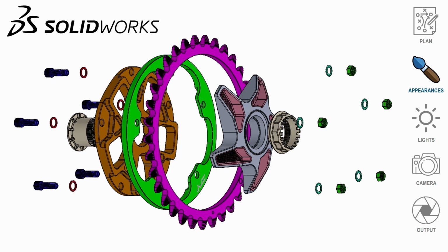Usually what I do in this case is, in SolidWorks you have in your appearance pane a default color that you can just drag out, and it's not any real appearance, it's just a color. If you hold Alt on your keyboard, it'll automatically pop up the box to start editing it. So I usually Alt drag the default color on there and pick an RGB value. Then I take that appearance and apply that RGB value to whatever it is that I want to be grouped together, if you will, as an appearance.